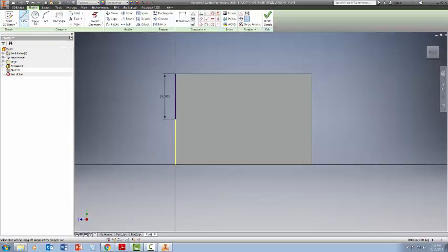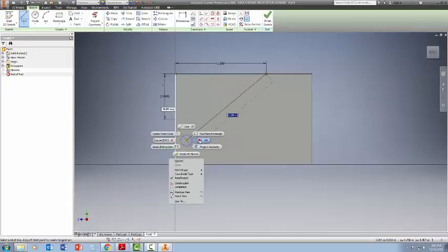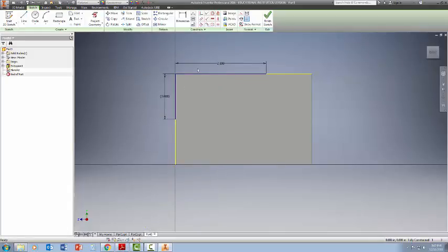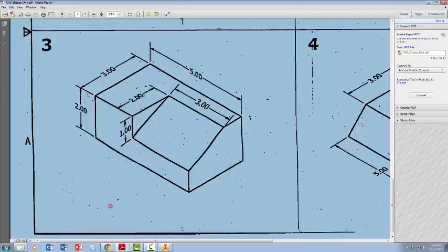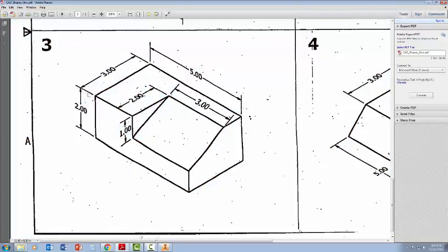Go back to the line, click again at that same corner. I went over perfectly 90, or in this case it's 0 degrees. I'm going to go over how far? 2 inches. Alright, if I right click, go to OK, I have a 1 by 2 inch line. If I look, I have a 1 by 2 inch line. And now I want to connect this diagonal. Okay, let's connect the diagonal.